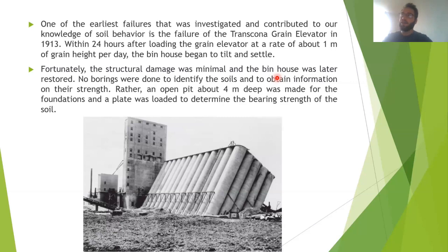So we usually do pile walls because it's easier. You just put the machine there, drill the piles, it goes really quickly, and you just excavate. And if you have a deeper one, you can put bigger piles, you can put anchors there, and that's some stuff you're going to model by the end of this course. And I'll show you how it actually works with slopes.